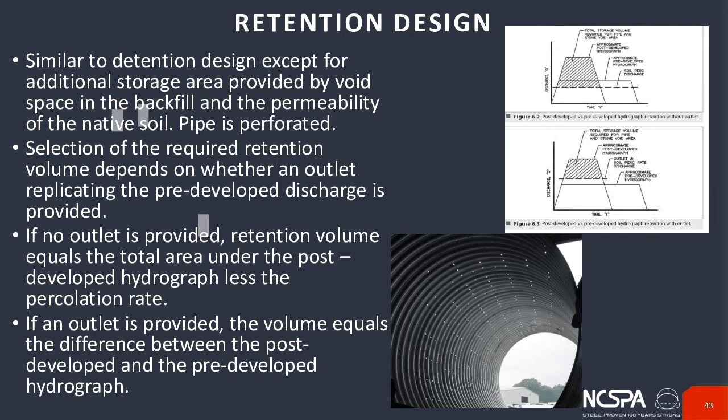So I'm just going to talk a little bit about the design of these types of systems, and how it's a little bit different from detention. But it is very similar in the design concept, except for the addition of the void space and the backfill that we're taking into account, and the permeability of the soils. Obviously, all of these pipes are going to be perforated.